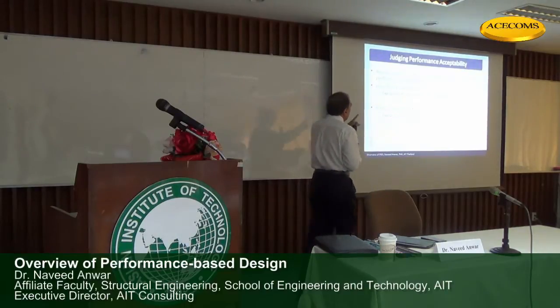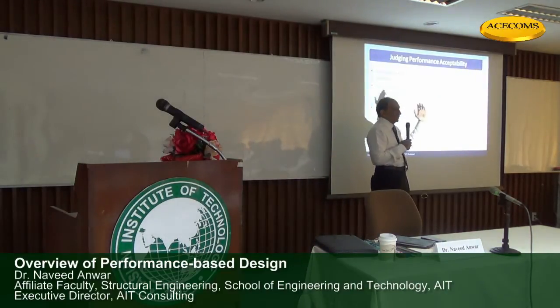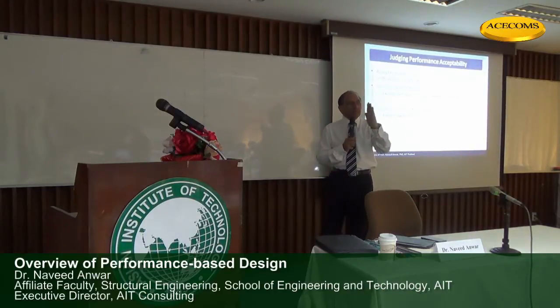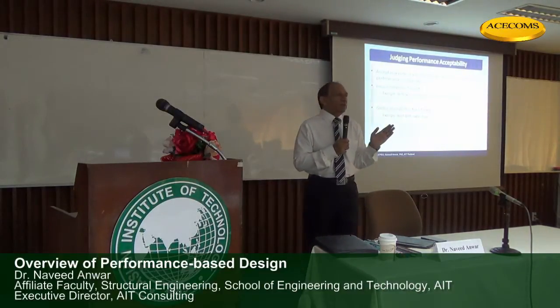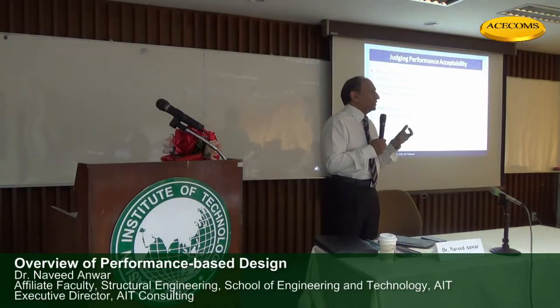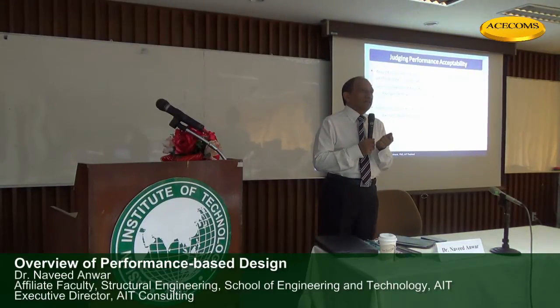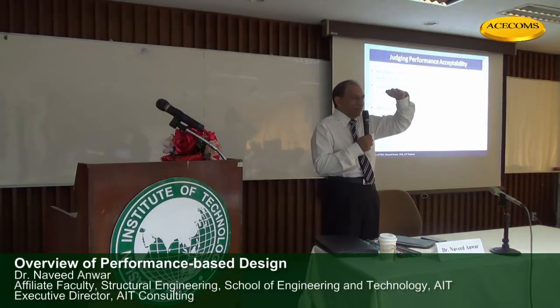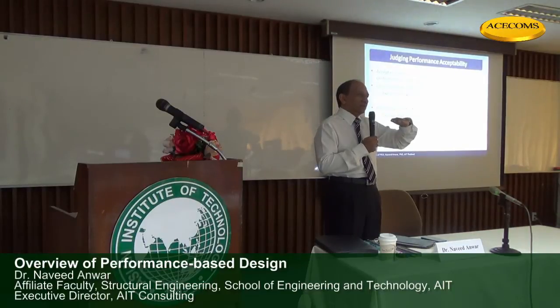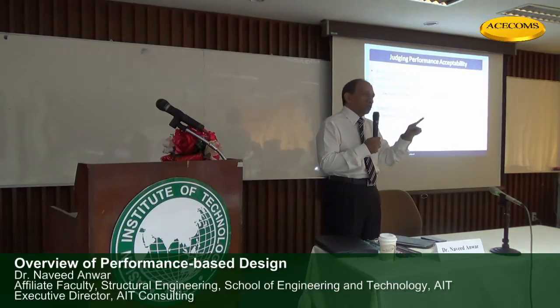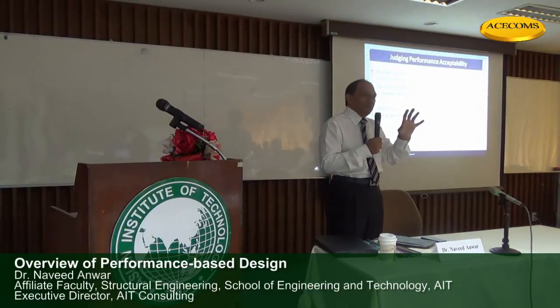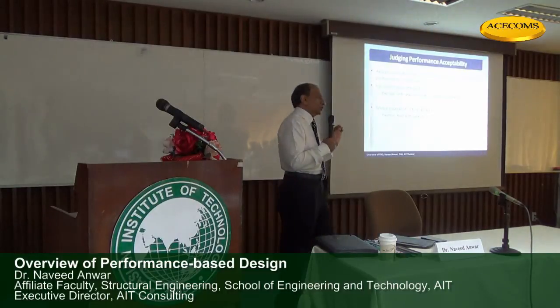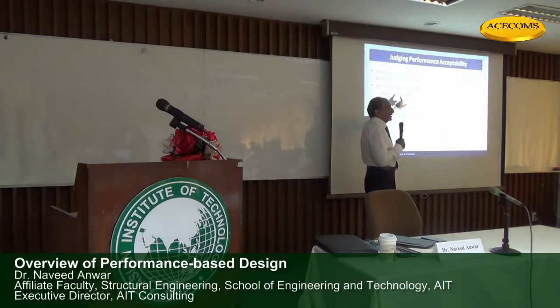Those are drift ratios, most important. How much the building will tilt. That will tell you almost everything about the building that you want to know. One of the most important key indicators that we check in a building is the drift ratio. How much one story will deform with respect to another story. Because that has everything built into that. Damage, structural damage, non-structural damage, P delta effects, everything is related to that particular number. So we try to measure drift ratios very, very seriously.